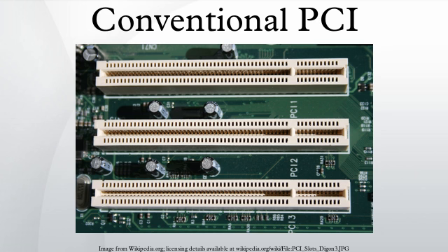Mixing of 32-bit and 64-bit PCI cards in different width slots. Most 32-bit PCI cards will function properly in 64-bit PCI-X slots, but the bus speed will be limited to the clock frequency of the slowest card, an inherent limitation of PCI's shared bus topology. For example, when a PCI 2.3, 66 MHz peripheral is installed into a PCI-X bus capable of 133 MHz, the entire bus backplane will be limited to 66 MHz.